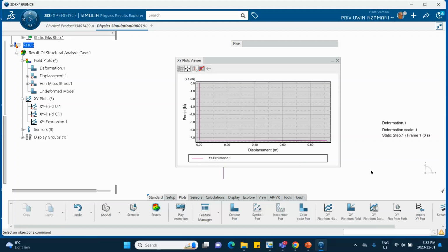Linear buckling analysis is cheap, but it will give you a value which is very approximate and is usually higher than the actual buckling load. Okay. Nonlinear analysis, if it's done properly, is what actually gives you the correct buckling load, which is usually always lower than the one from linear buckling analysis. As a matter of fact, you put the cursor here, you can see that, see this? This buckling load is 7.3, which is lower than what the other fellow got.